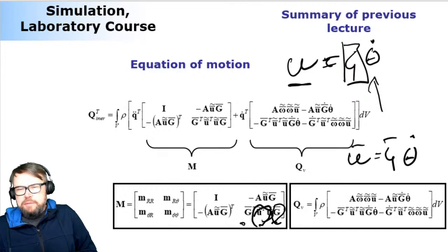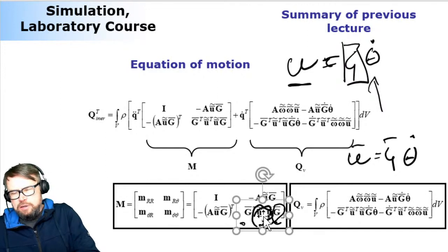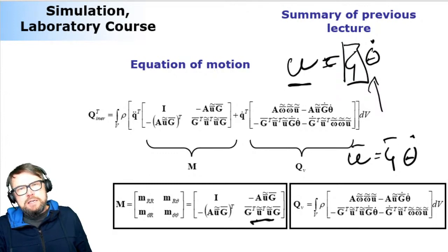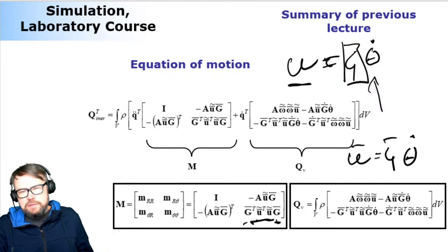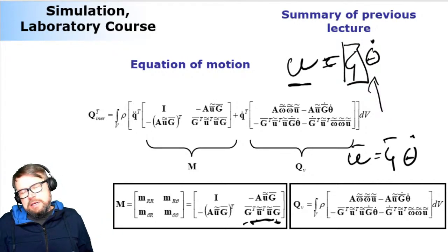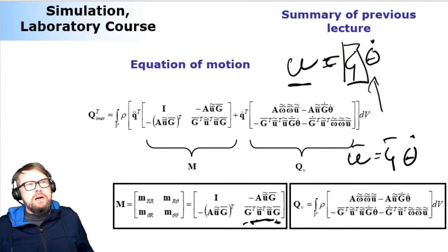The one in the middle is the inertia tensor, which consists of mass moments of inertia and mass products of inertia, and it can be related to any set of generalized coordinates with the help of G. And that, of course, tells you that the G expression is a function of what kind of generalized coordinates you are using.